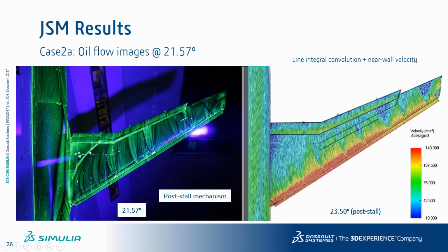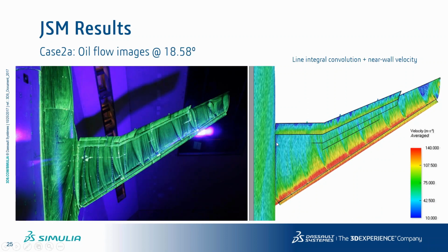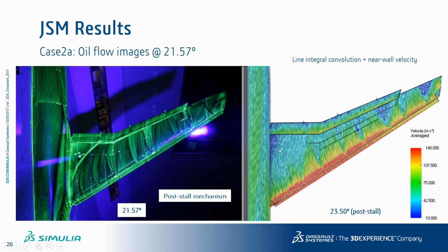forming from now not only the wingtip, which is again much larger still than the previous angle, but also from the fuselage, okay? So you've got a large separation that occurs in the intersection between fuselage and wing, basically, which is especially happening in this back region here. And this is also something we observed in XFlow. As you can see, this region increases, and at the next angle, this region increases much more. So we've got a large separation that starts growing here and there, in that direction.